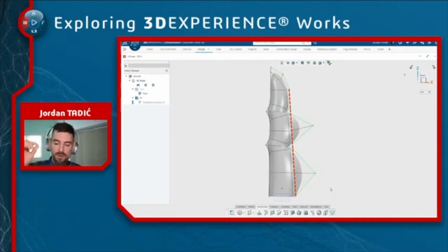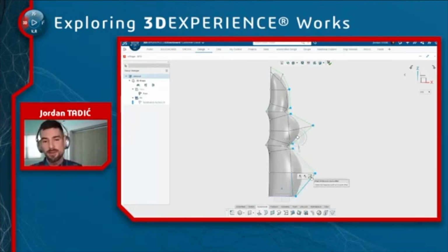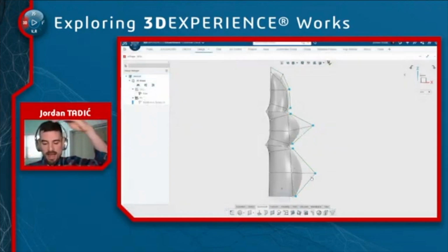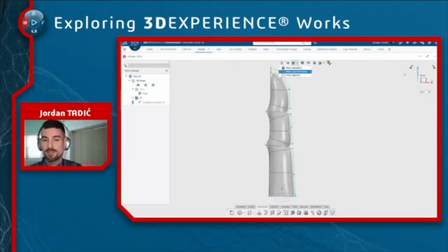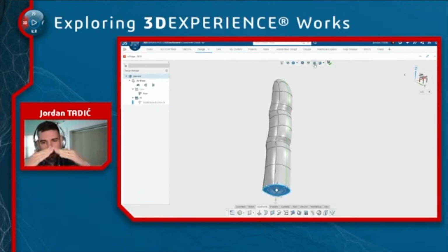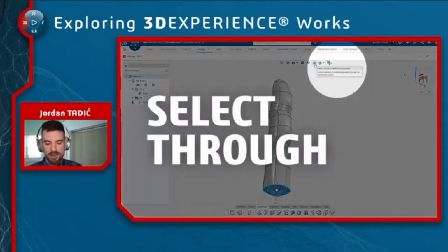What you want to do is pick the 2 points first that are going to define that theoretical line. And then you can control select the rest of the geometry, whether by box selecting or individually selecting. On the context menu, you'll get the option to align vertices to each other. What it does is look at the first 2 selected points, create a theoretical line, and flatten everything to that line, which is a super easy way to handle those times when the cage is inverted and you want it to be perfectly flat. You can pick those points and flatten it out very, very easily.